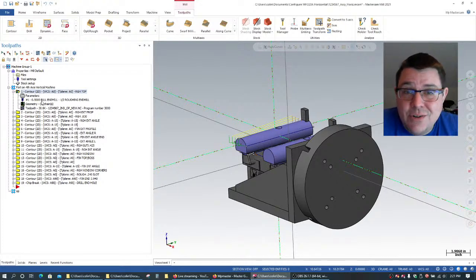So you might have your material described there. You might have a tool list. There's all kinds of things that you could end up describing up in the header. And after you get through the header, you're generally going to come to your first operation. So your first operation is going to be output through the start of file post block. So it's PSOF. We'll take a look at a couple of these things.